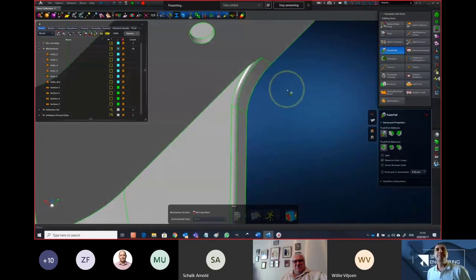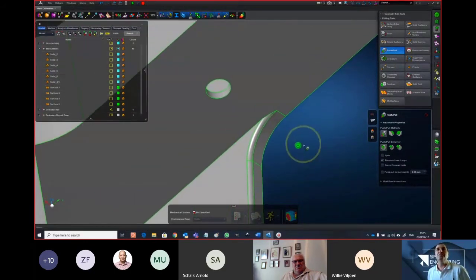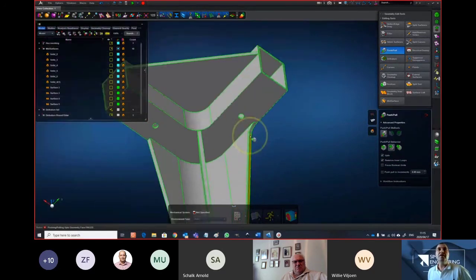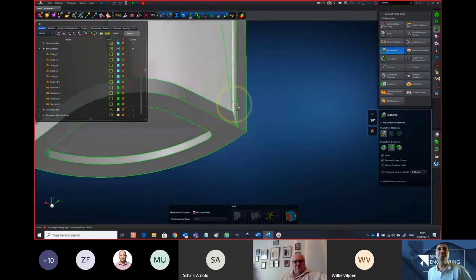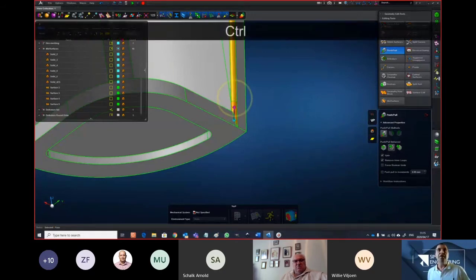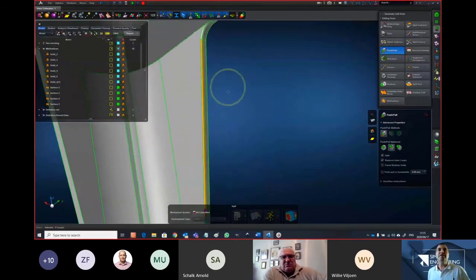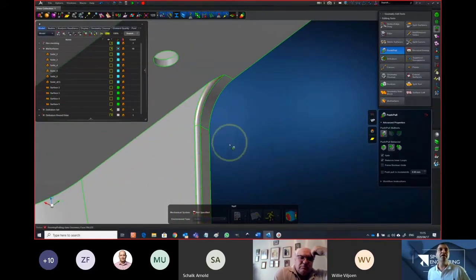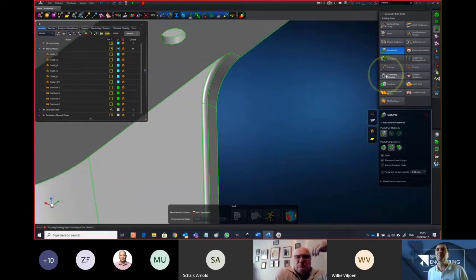So there's something similar happening in this case, although it's not quite clear. So one option that I'll try is to use my push-pull up to tool and select this face and pull it up to that one. Now, strangely enough, this one fails as well. So it means there's definitely something going on with this piece of geometry that does cause this issue. I can try and select multiple ones and see if I can push them up to this one. And for some reason, it also fails.